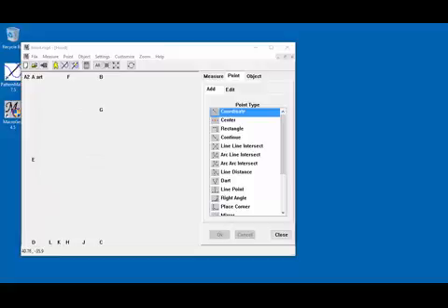We are also going to need to place points D2, K2, and L2 on a curve below the bottom of the hood. These points are based on D, K, and L. In other words, points A, D, K, and L aren't really part of the pattern. They're intermediate values used as part of a two-step process to calculate the actual points needed.